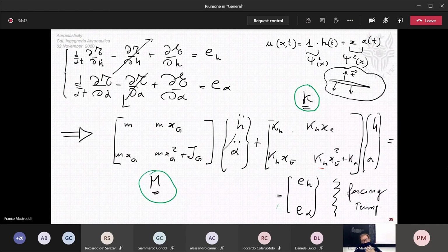The physical force is a time-by-time pressure distribution given by the vector t at any time. But the forcing term you have to write here is not your original physical vector. Following the Lagrange equation of motion theory, this generalized force is the projection of this physical vector onto the corresponding mode shape.